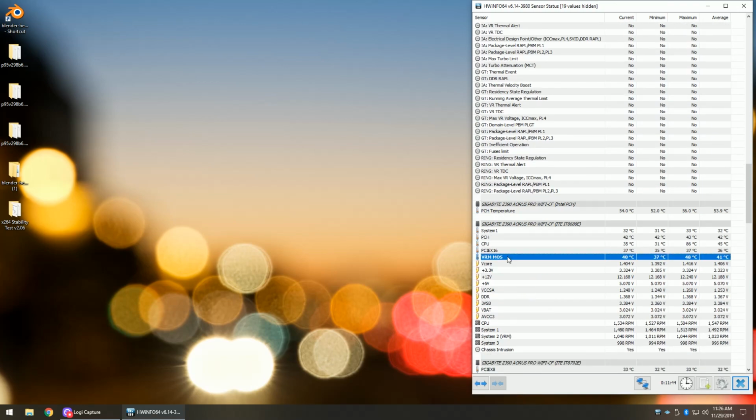A lot of times people are setting up their overclocks by setting a frequency but not setting their V-core or LLC and letting the motherboard just have its auto setting. The auto setting on the motherboard really does not know what the optimal voltage setting for your processor is, and it usually overvolts it to remain as stable as possible. The problem with that is it might exceed the 1.4 volts stable for the processor, which can cause processor degradation, causing it to require more voltage or lower frequencies over time.